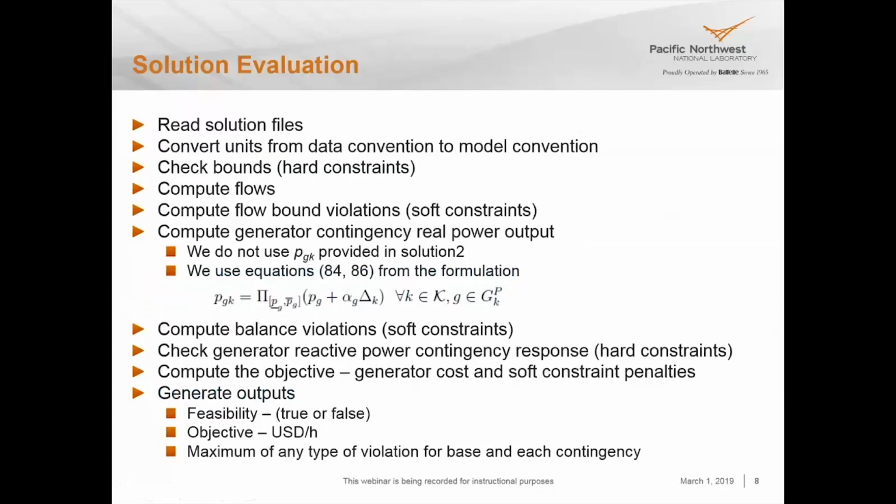And here's how solution evaluation works. So again, we read your solution files. We convert the units from the data convention, that's mostly megawatts, et cetera, to the model convention, which is mostly per unit. We check the bounds on some of your variables. These are hard constraints.